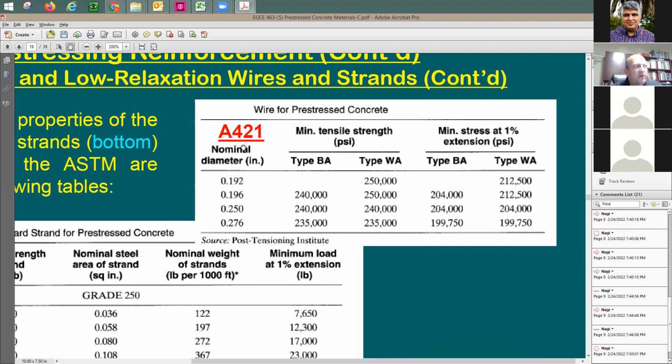Then you say, where do you think I'm going to apply this? What structural members? You say maybe in planks. The hollow block, if you remember, the one that has circles, like the concrete slab. For the short span, maybe I can do wires in there. I'm not going to do strands. Then this is going to be very good for that application. Only for small spans and small work, in pre-tension, not in post-tension. Generally speaking, this is used for pre-tension, for small construction and small spans.